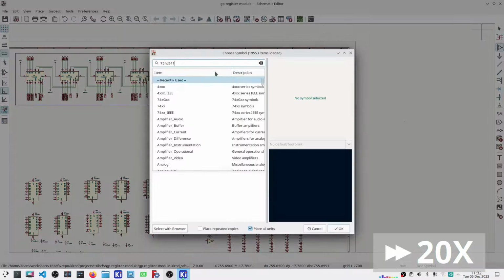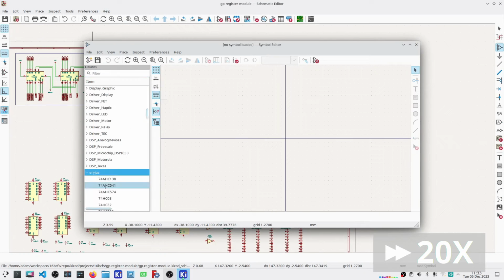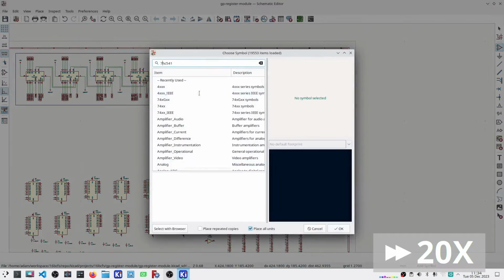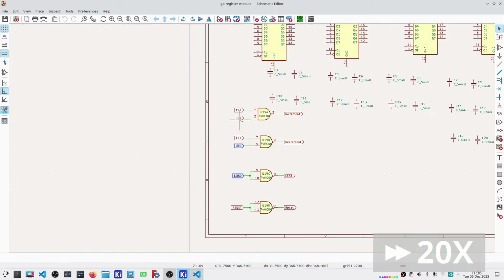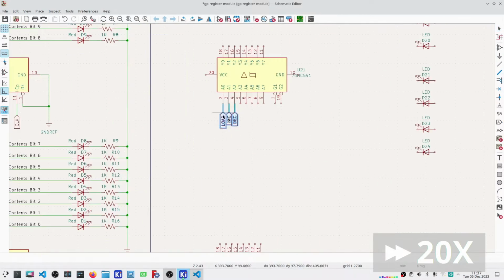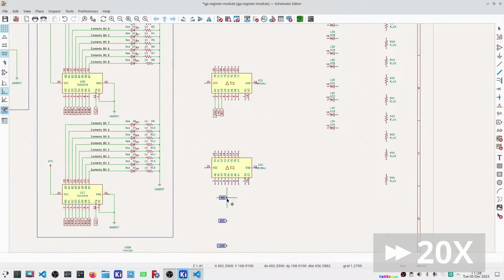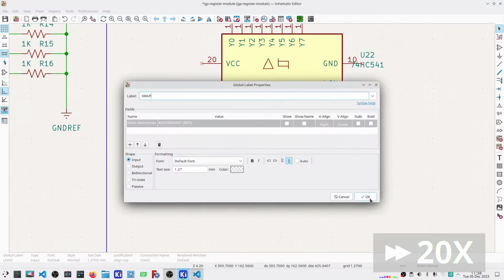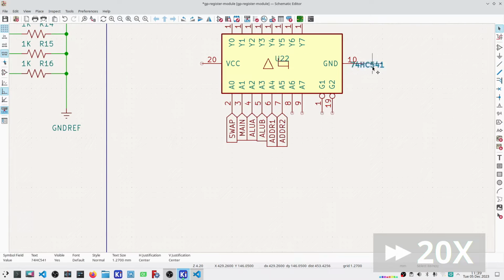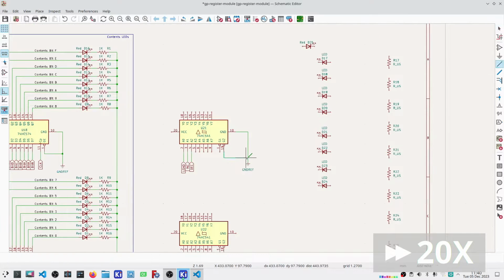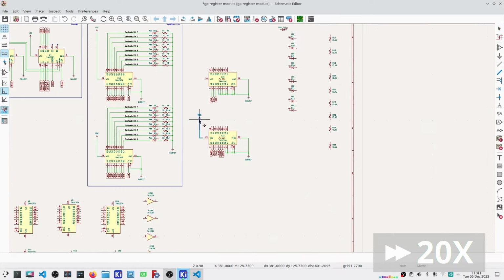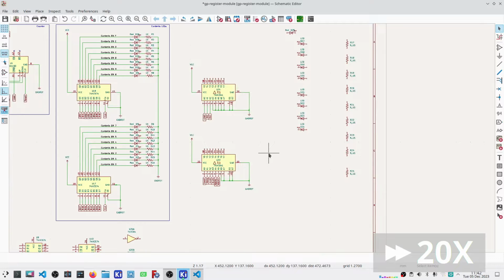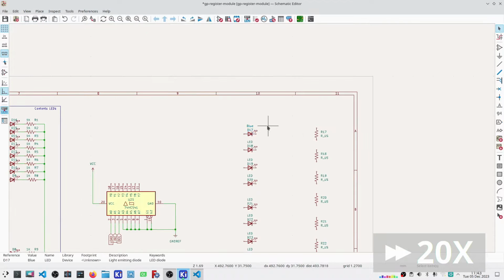Now, as I mentioned before, I forgot the line drivers for the control LEDs, so I have to go pull those into the schematic. I also want to take a minute and talk a little bit about a change in how I am going to display the control signals. Rather than shaping the control signals at the control logic and then risking losing them at the actual device, I'm going to display the control signal for the entire clock cycle that they are relevant.